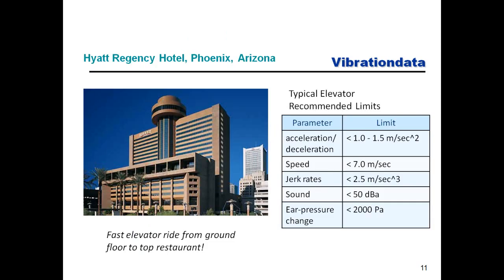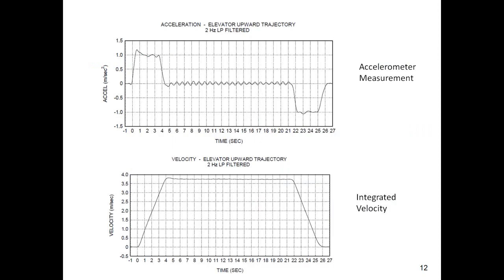So what I actually did is I had a laptop computer, and this was about 10 years ago, with a little student variety data acquisition system and an accelerometer, and I went and actually measured the elevator vibration for a straight nonstop ride from the ground floor up to that revolving restaurant. On the top here you can see the acceleration, and I've made a note that I've done a 2 Hz low pass filter on this data to filter out some high frequency noise.